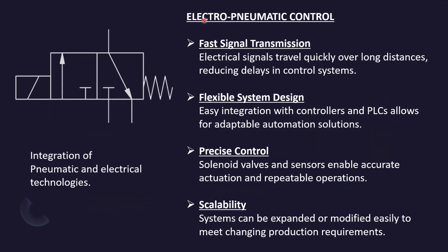All right, electropneumatic control. So, for example, here, these are all familiar symbols for us right now, except for this little guy right here. Remember, we have that. This is our actuator. Here's a symbol of... Remember what that would be. How many ports does this one have? 1, 2, and 3. Okay, so port 1, remember, is the main air supply.